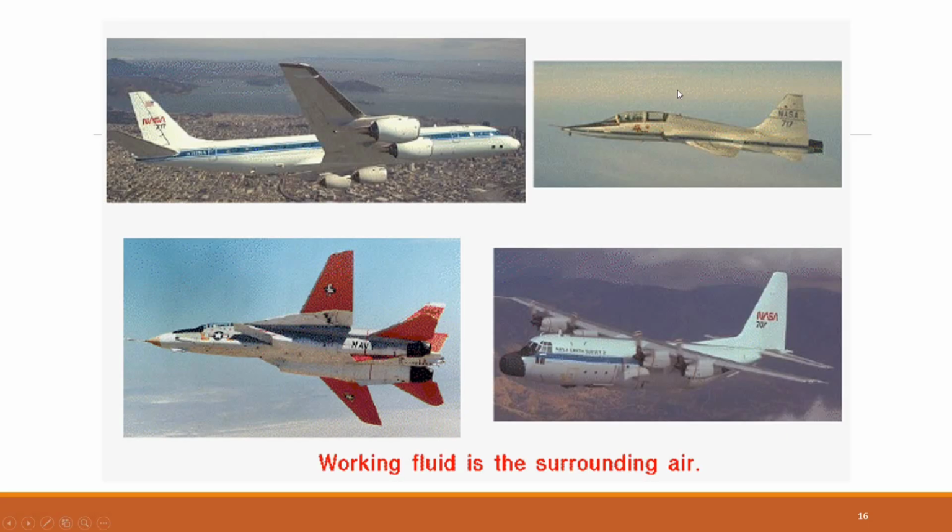Finally, at the upper right, there is the T-38 trainer jet, an aircraft used to teach new pilots how to fly high-performance jet aircraft. Because it is designed primarily for training rather than combat, it does not require the extreme thrust levels of a fighter like the F-14. The T-38 uses 2 turbojet engines, a simpler and lighter type of gas turbine engine that provides smooth, predictable performance, ideal for teaching pilots the fundamentals of jet flight.